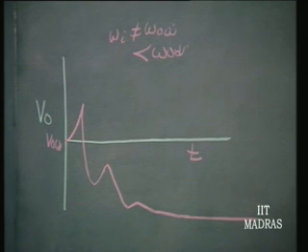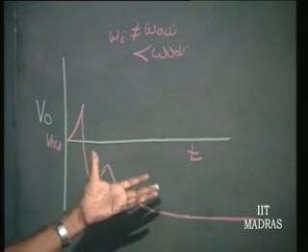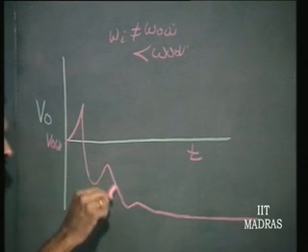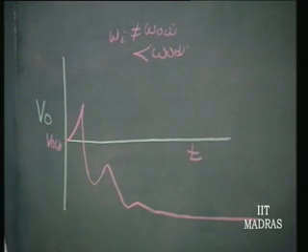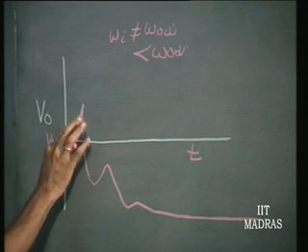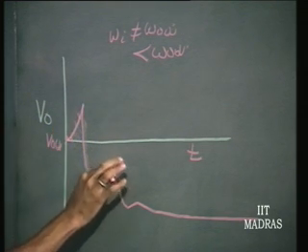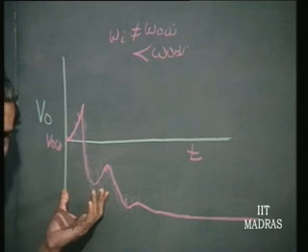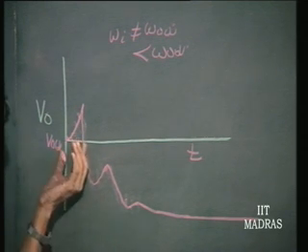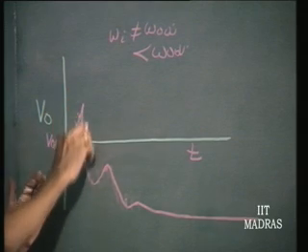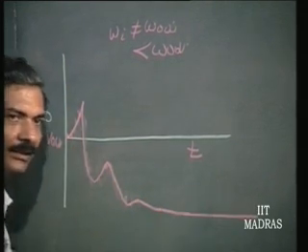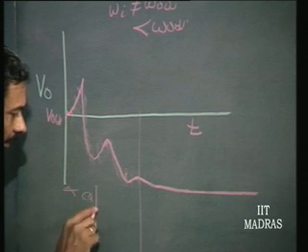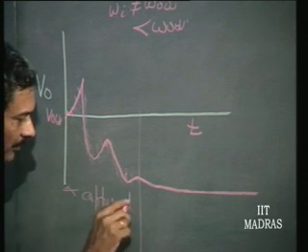That obviously depends upon the low pass filter capacitor, the averaging capacitor, but this is the kind of waveform, with a lot of high frequency superimposed over it, because that is not going to be totally eliminated, but will be attenuated considerably. So, you will see a waveform of this type, and this is called the capture time.